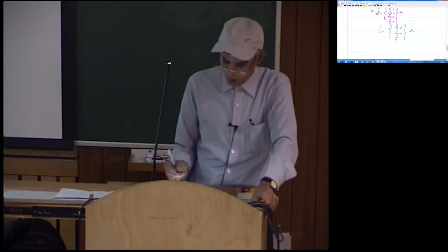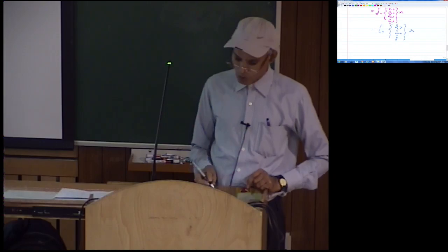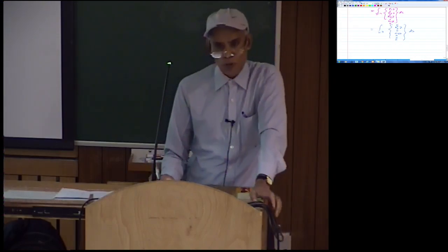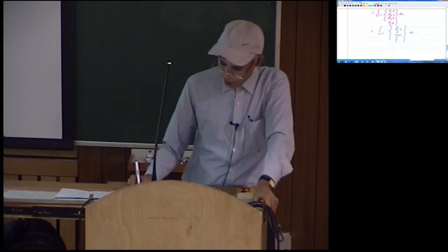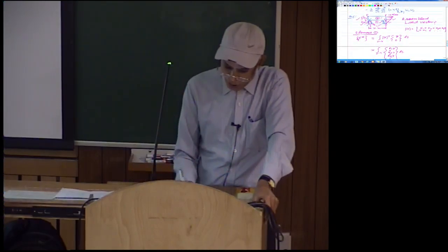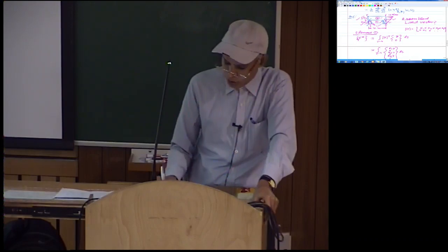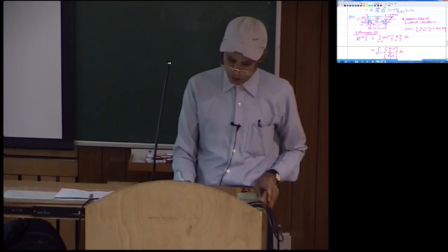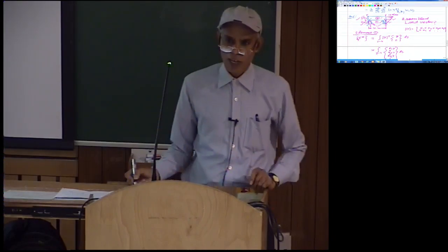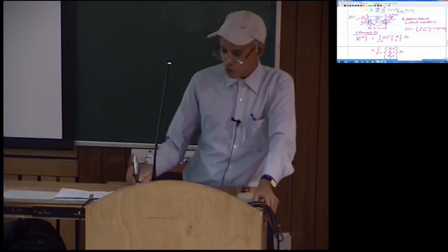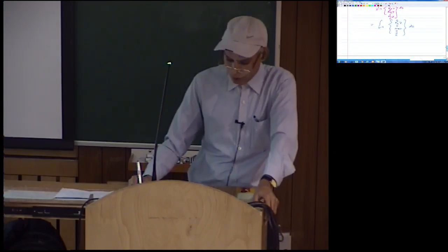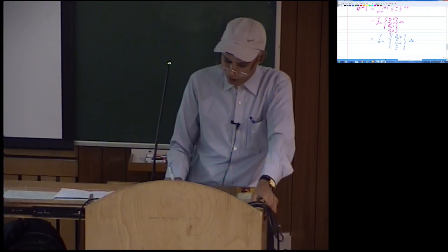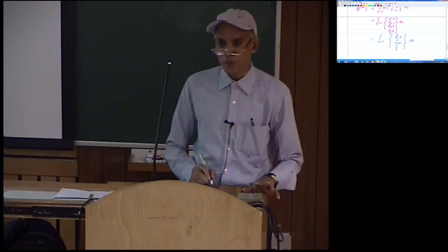ds. And now the evaluation part comes. So you have to obviously write here N1, N2 and N3 of course in terms of xi and eta. Along this edge, each of these elements is going to be mapped to a square in the natural coordinate space. So along this edge, your xi is going to be +1. So it's only eta which is varying. So if you evaluate these shape functions, they are only in terms of eta, and you also need to write y in terms of xi and eta.